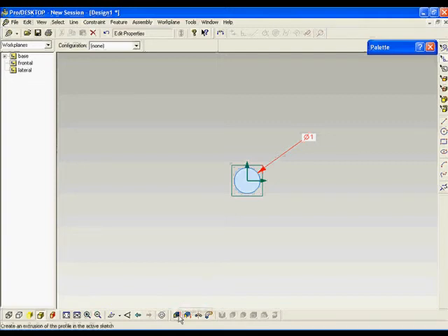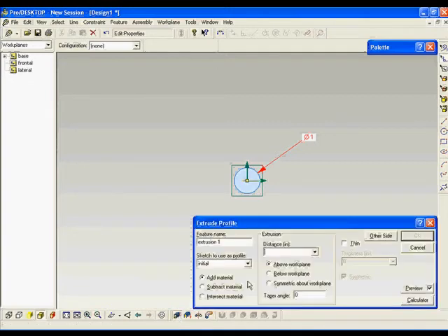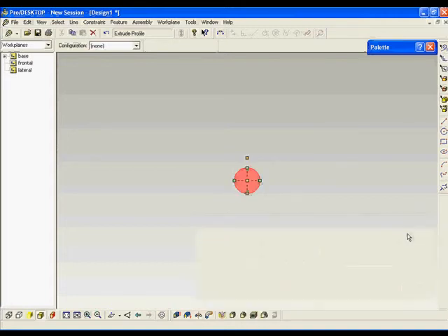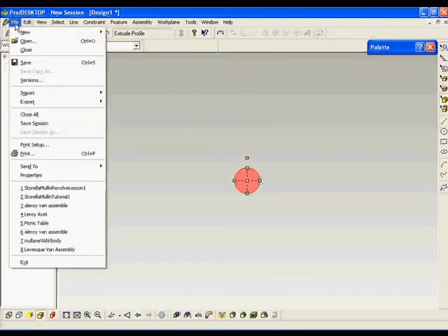This orthographic two-dimensional view is a circle. We want to extrude it 12 inches so it becomes an axle, or a 3-dimension. That third dimension will be in the Z direction, and that becomes a pictorial view. So the pictorial view is an axle. The two-dimensional orthographic was just the circle.